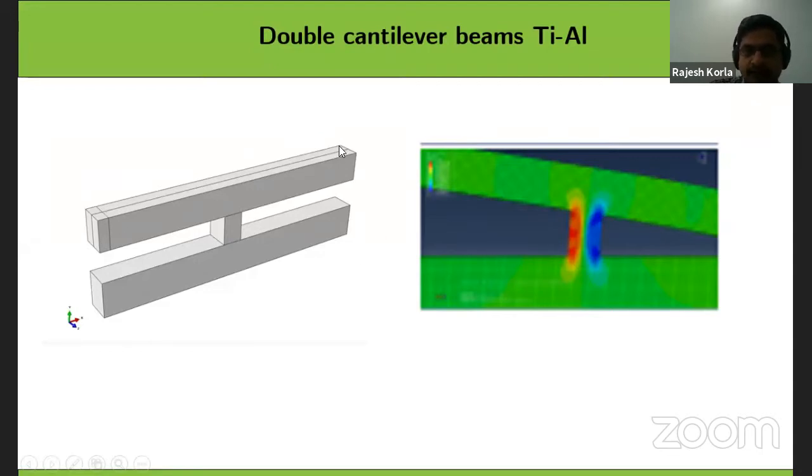For example, you're applying load at this position using the nanoindenter, then this portion will be compression, this portion will be tension. Then if you change the load to this one, then this portion will be tension, compression, this portion will be tension. So you can apply the load, tension, compression, cyclically. In the same sample, one time you're applying tensile stress, and another time you're applying compressive stress. So you can see the effect of cyclic loading on the mechanical behavior.